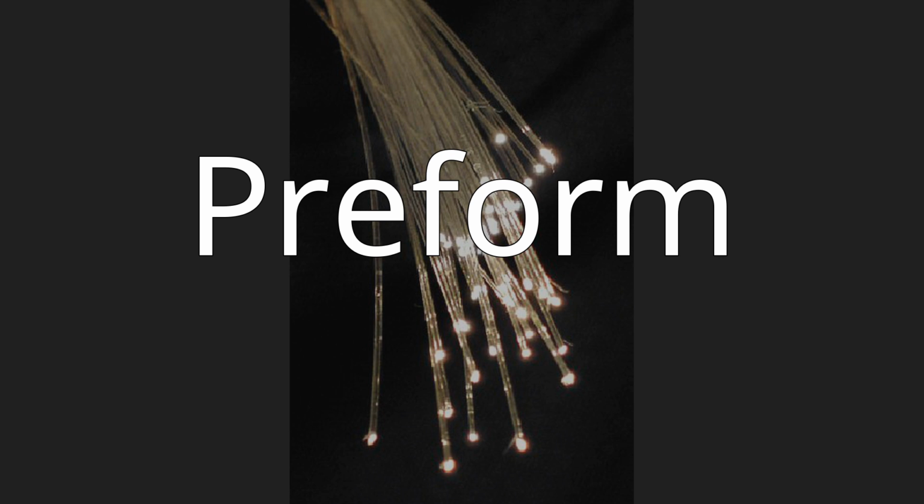The deposition is due to the large difference in temperature between the gas core and the wall, causing the gas to push the particles outward. This is known as thermophoresis. The torch is then traversed up and down the length of the tube to deposit the material evenly. After the torch has reached the end of the tube, it is then brought back to the beginning of the tube, and the deposited particles are then melted to form a solid layer. This process is repeated until a sufficient amount of material has been deposited.